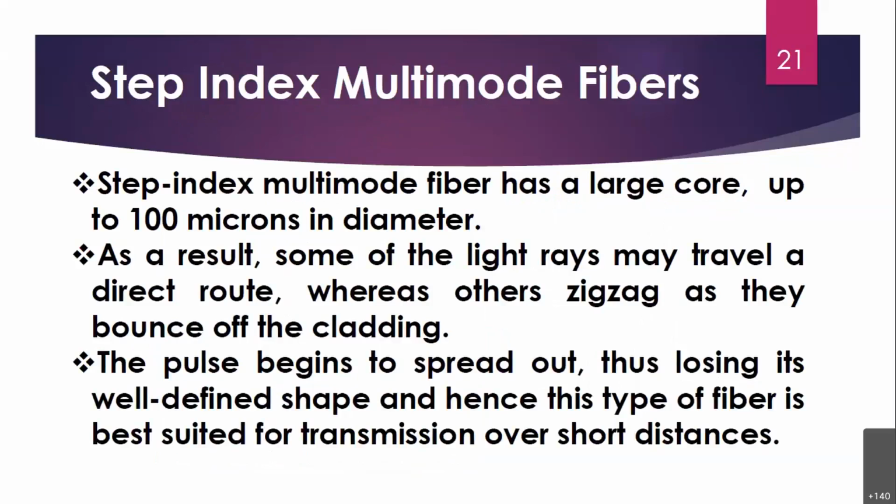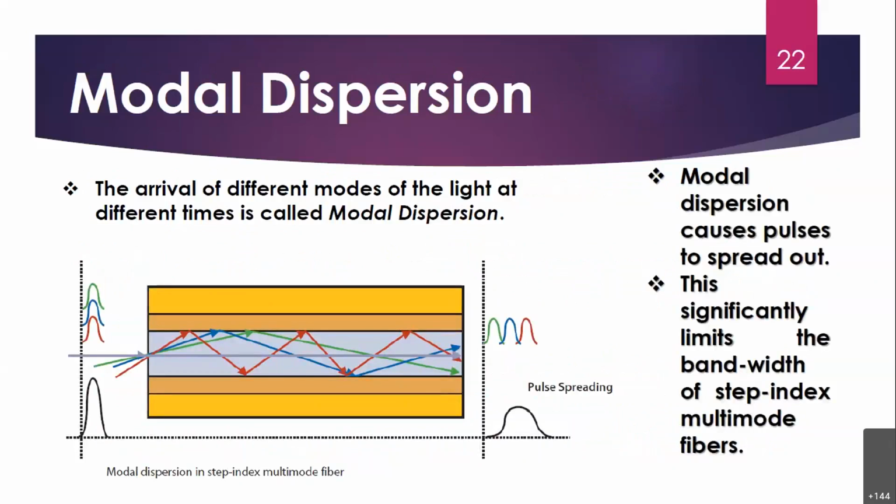And then we covered a few other details about step index multimode fibers: their diameter, core diameter, etc., and the paths followed inside the optical fiber. And what is the outcome we get from this optical fiber was also discussed. Basically, your pulse is getting spread at the end. That's how we discussed this last time. And this was the phenomenon responsible for such problems: modal dispersion.